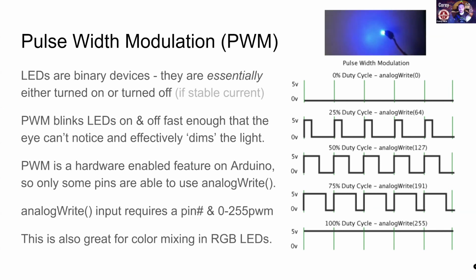It's just playing with time and your sense of persistence of vision in order to get reduced brightnesses, which is actually, I think, really cool. But it's definitely a subtle art for how this works. And it's a lot of technical detail, but when you analogWrite some number that's lower than 255, you'll just see, oh, it's brightness, and it just works, which is actually great.